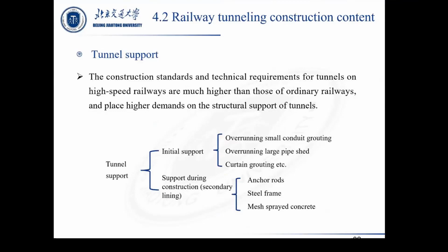First, for the construction of a center wall and cross partition in a large-span tunnel with soft surrounding rock, and then the other side of the tunnel is excavated and the construction of the cross partition is finally completed.